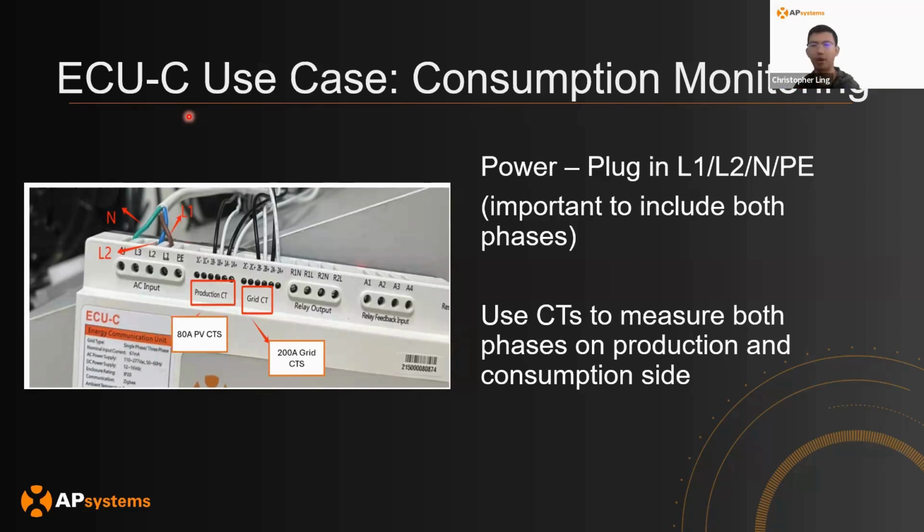So the number one parameter I always look at is the VMP, the voltage that the panel operates at when it's pushing maximum power point. The key thing is that the panel's VMP needs to be within what our microinverter calls the peak tracking voltage range, and for the DS3s, it's 28 to, I want to say, 45.